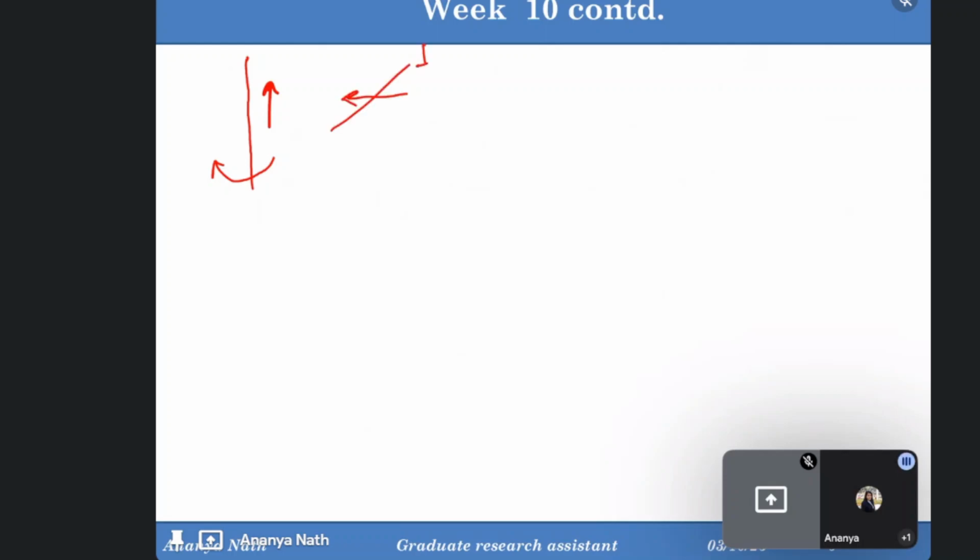Suppose this is one edge dislocation, and this is one screw dislocation. As I said, the screw dislocation will have two different arrow directions, because screw is like the real meaning of screw. It's moving and it has some axial movement.